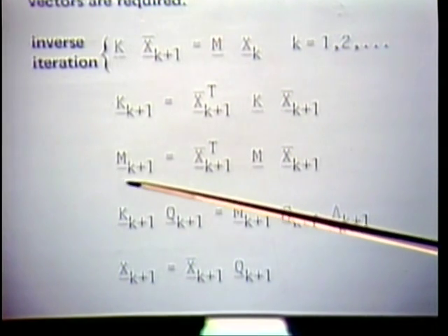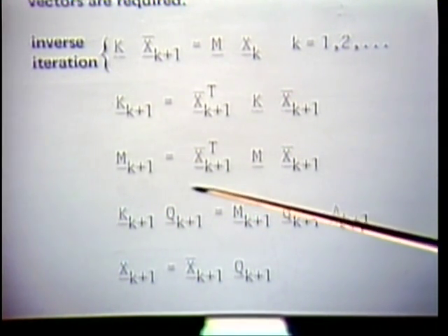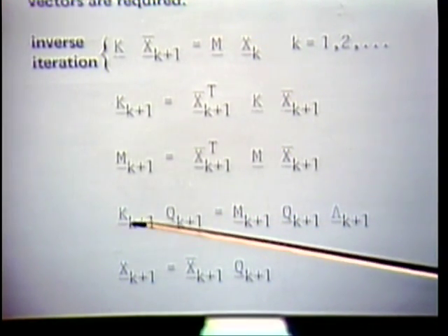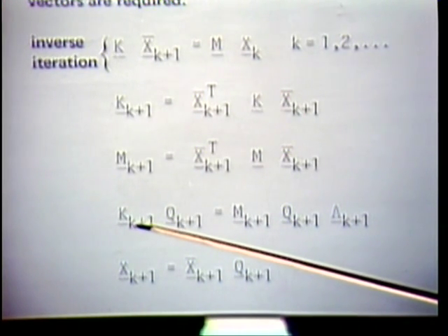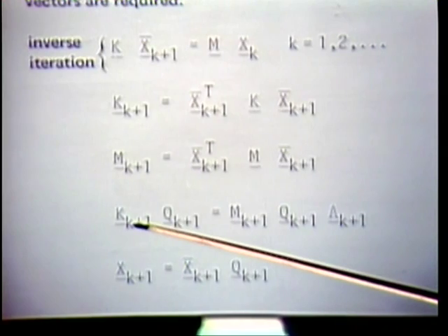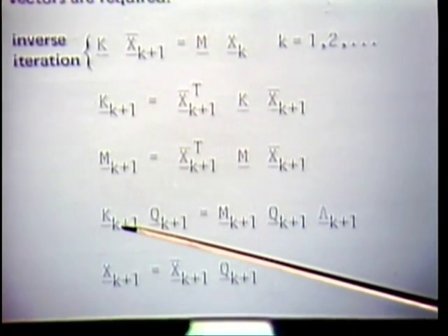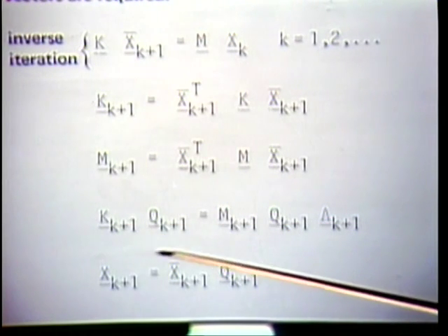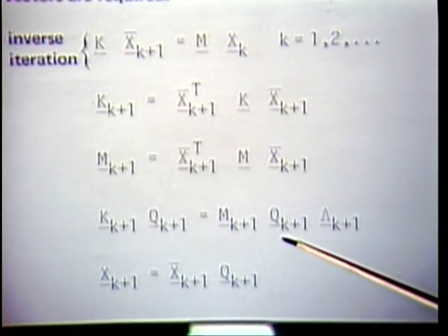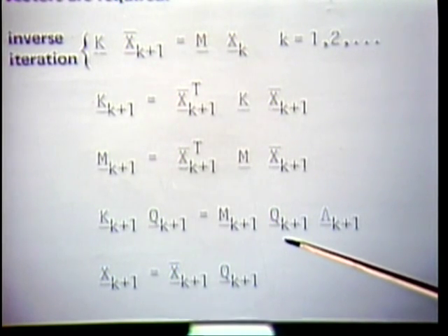Notice that the solution of this eigenproblem, q by q, might be a 50 by 50 matrix here, a 100 by 100 matrix, maybe up to a 200 by 200, but that already would be a large number of vectors that we're using, a very large number of vectors. This solution of this eigenproblem can be effectively achieved via the generalized Jacobi method, which I referred to briefly earlier.